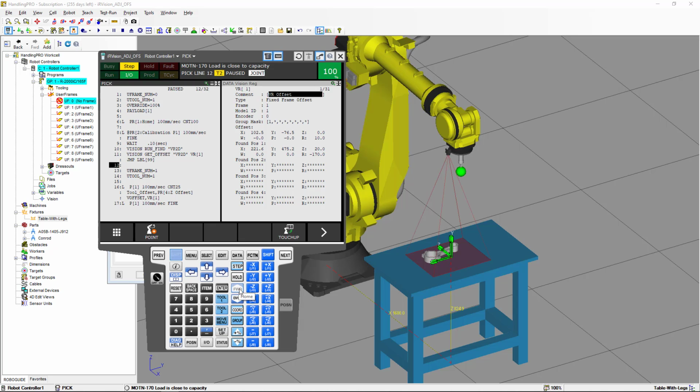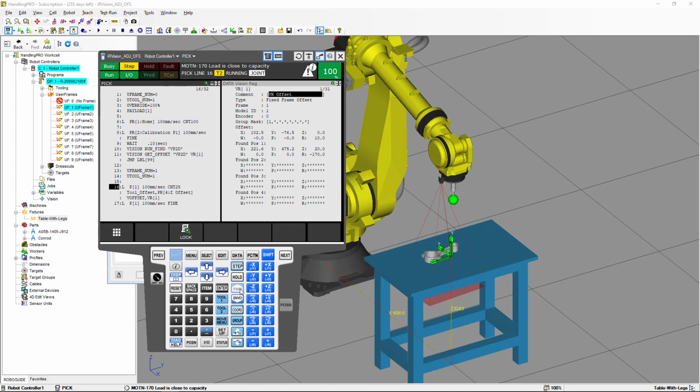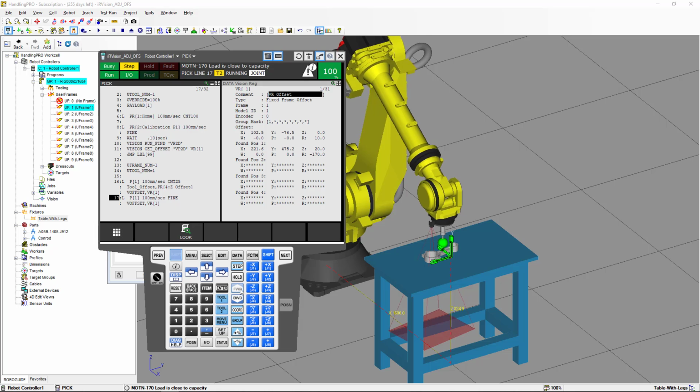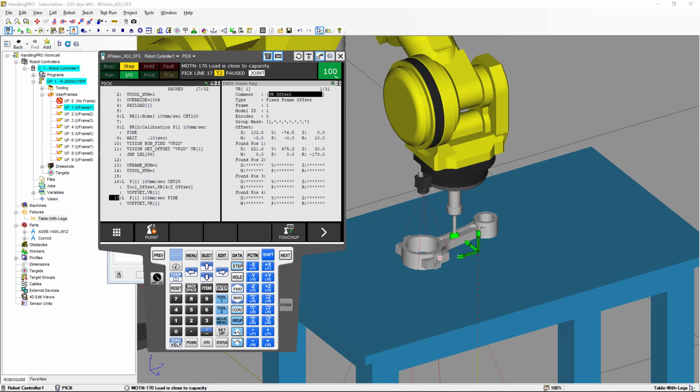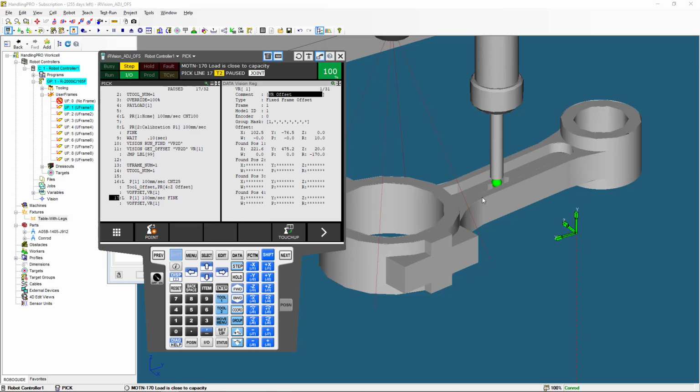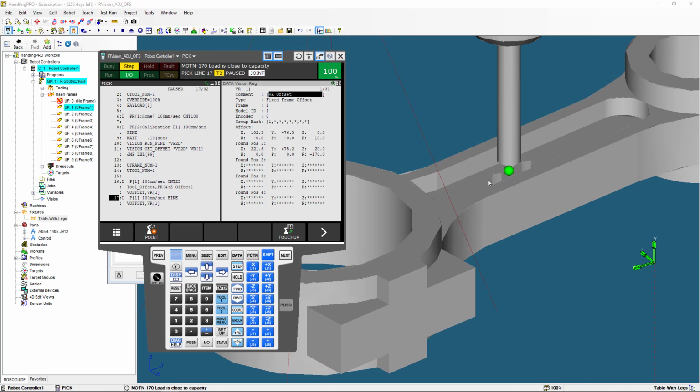We're going to keep running. We're going to go to the touch position. And let's look now at what happens. So now when we change the rotation for the part, we are not able to go back to the same position. So now we have an offset. This is the way that you're going to identify that you have a problem, that something is not right, that you made a mistake at some point during the calibration grid frame setting. So we need to find a way to correct this offset.